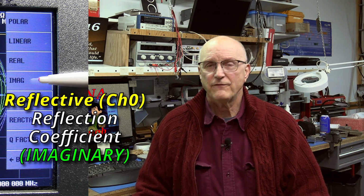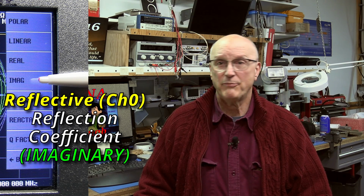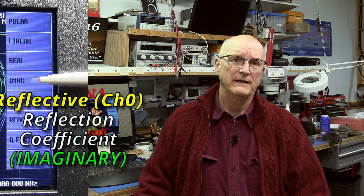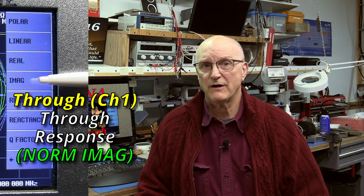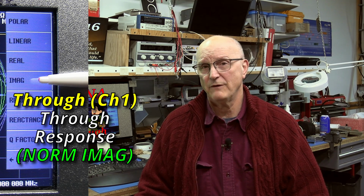As you probably might guess, there's one more option directly related to the polar values. The last of the options that is directly related to the values provided with the polar display option is the IMAG option. This is short for imaginary. In the reflective mode, this is the imaginary portion of the reflection coefficient. In the through mode, this is the normalized imaginary portion of the measure of the signal coming into channel 1 from channel 0. The next two display options relate to impedance measurements only.